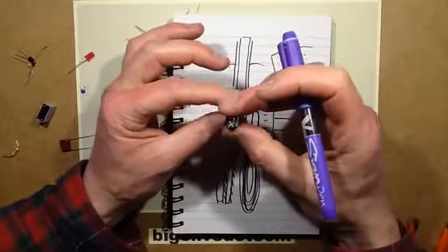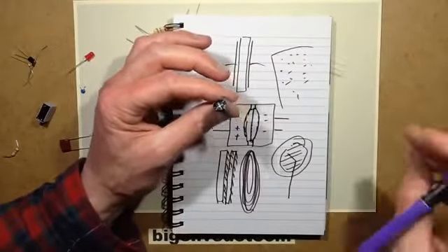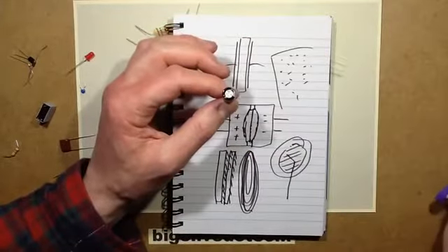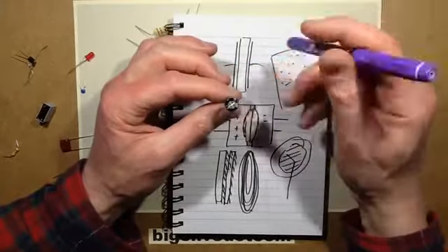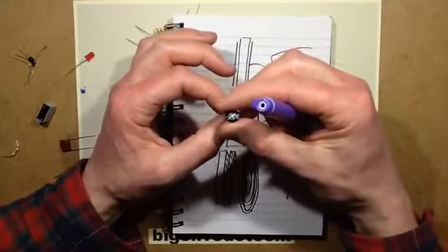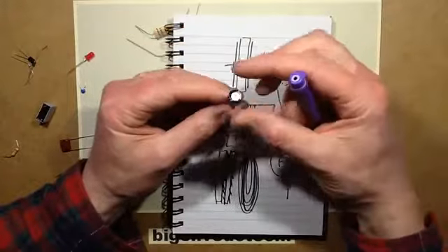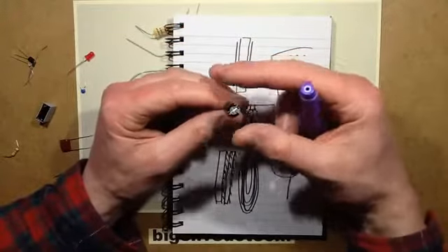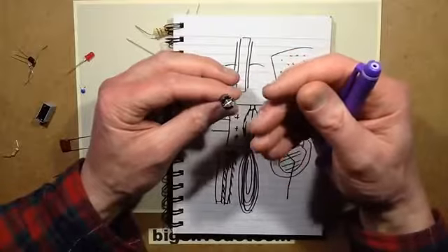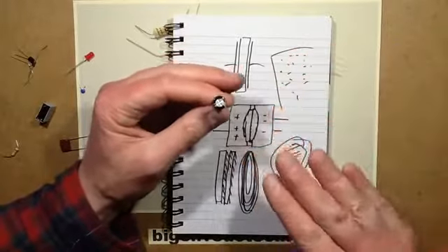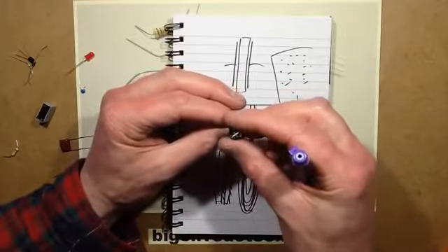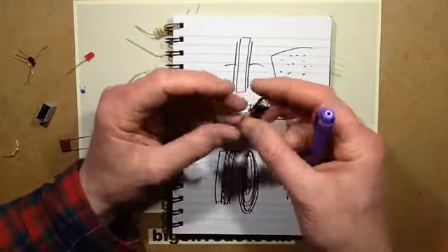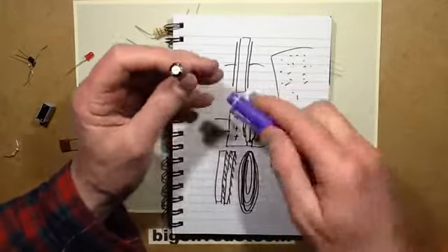Traditionally, all the old video games from the 80s tend to suffer problems after a while with what's called drying out of the electrolytics. They still measure the correct capacitance, but their equivalent series resistance, the resistance to current flow through them, changes, it increases. And what that means is that they stop doing their job properly.